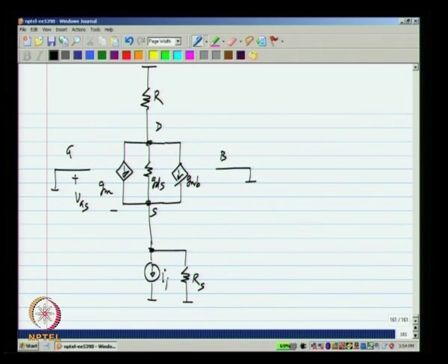Okay. So, without this we have already determined the answers, that is the output resistance is high, it is Gm RDS times Rs plus RDS plus Rs and so on. What happens due to GMB? Now, in this case the analysis is very simple, because this is VBS, okay, and let me call the voltage at this node Vx, VGS equals minus Vx and VBS equals minus Vx.